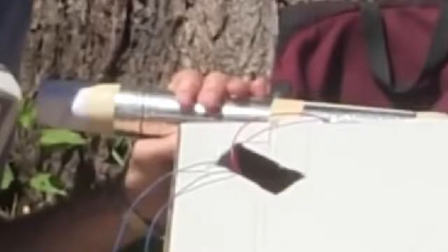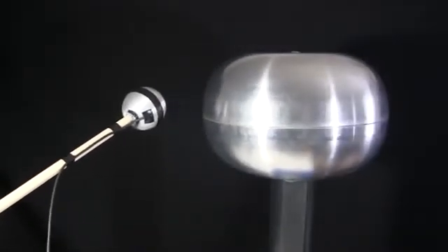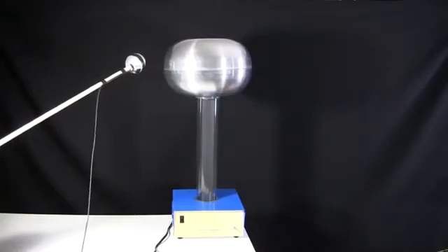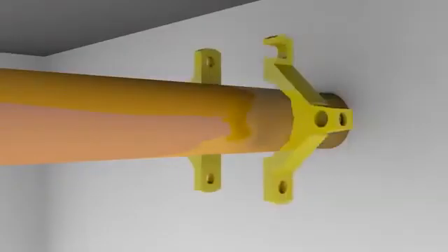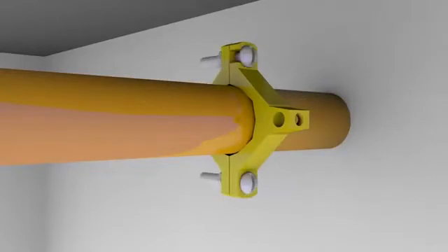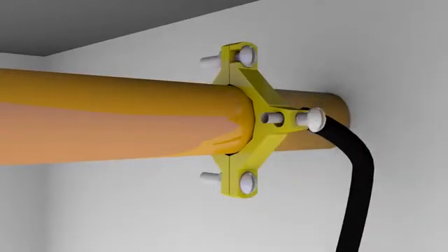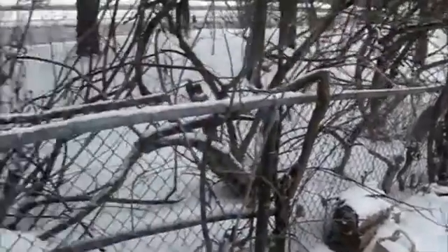Here, I'm the ground. Often when playing with high voltage, you'll have a ball that's connected to a wire going to ground, and make a spark by bringing that near a charged object, like this Van de Graaff generator. A fairly safe way to ground that, if you don't have a ground rod that you can connect to directly, is to find a metal pipe that you're certain goes into the ground. Like this copper cold water intake pipe from the city. Or this metal fence would do, since it makes plenty of contact with the ground.